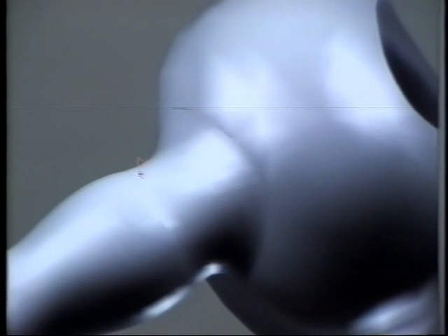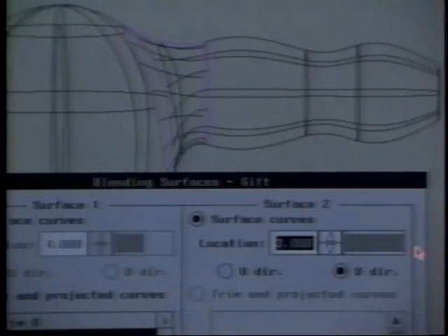We've got an imperfect blend here with curve fitting turned on. Optionally, one way we improve some blends is by making the blend overlap slightly with the base surfaces. To match the blend to the arm, we make it start not at the last chord of 3, but at 2.99. Now it looks much more seamless.